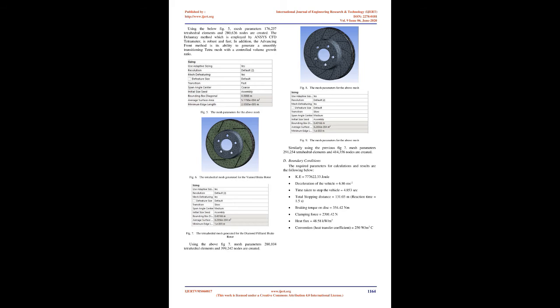The patterned pillar structure improves the cooling efficiency of the brake rotor by increasing the overall contact area between air and the rotor body. This type of design also takes advantage of the centrifugal force to force air from the inside of the rotor to the outside. The various pillared structures create multiple air passages and give rise to turbulent flow. This induces a more efficient form of forced convective cooling, lowering the maximum temperature reached by the component on prolonged braking operation, thus improving the durability.